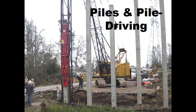Piles are practically similar to columns, and they have a similar and at the same time different purpose for construction projects. Where do we use piles and why do we need them? In certain situations where the soil is not stable and we need to put the structure on top of that soil, we will refer to piles. It requires engineering calculations to understand how big each pile should be and how closely you have to position the piles in the area in order to keep the structure on that soil.